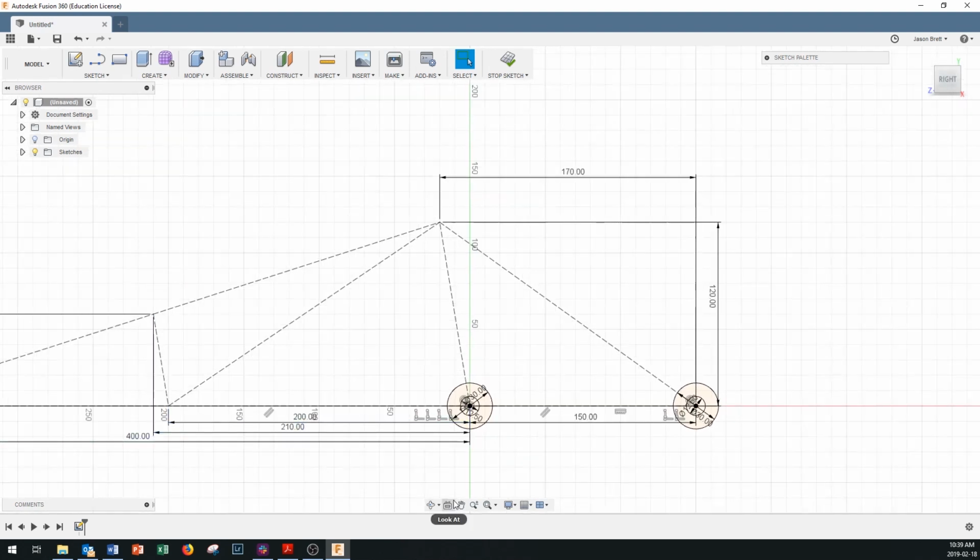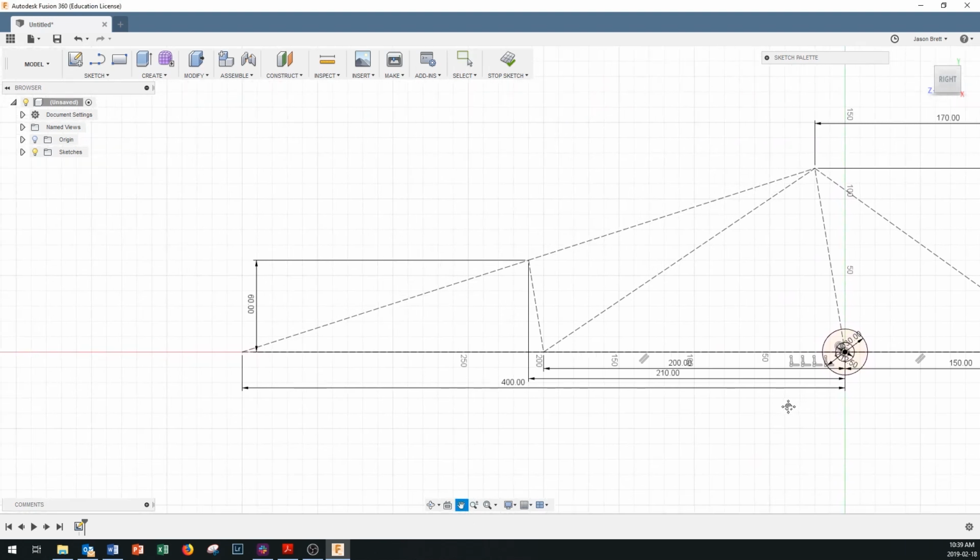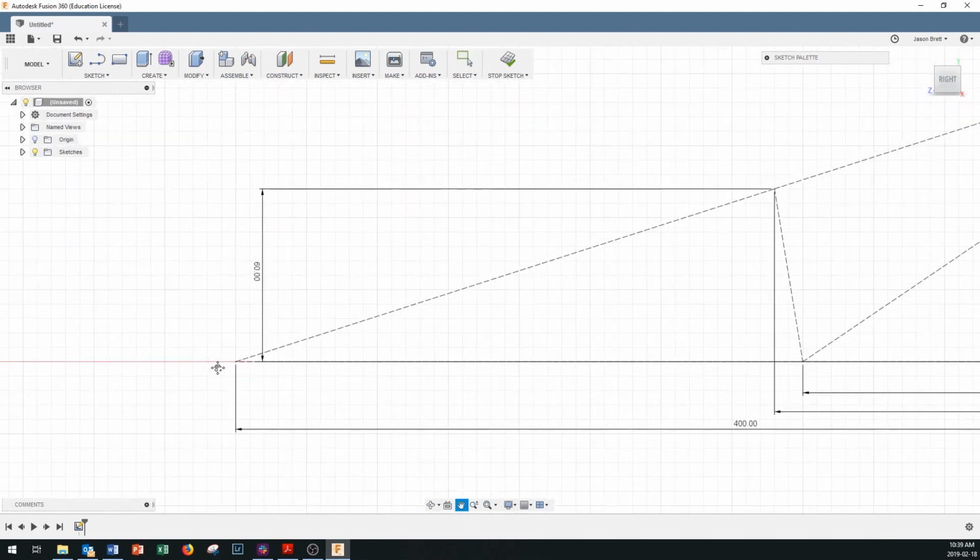We've got a pan key right down here in the middle of the screen. That's our hand for moving this around. And that lets us zoom in right out here at the end where we have our load. To get rid of the pan, just click on the screen and then C for center diameter circle and a 30 millimeter diameter circle and C, a 12.5 millimeter diameter circle right in there.